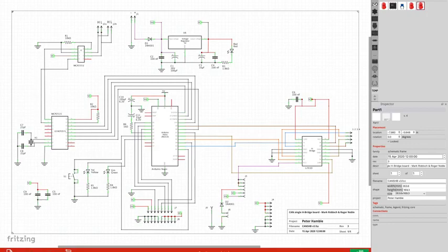Here's a board I've designed for our layout. It has an H-bridge. We can drive a stepper motor as well as a variety of outputs that can drive servos, light LEDs, receive inputs and so on, all controlled by an Arduino Nano. And it has a CAN bus or C bus interface to interwork with the MERG layout control bus.